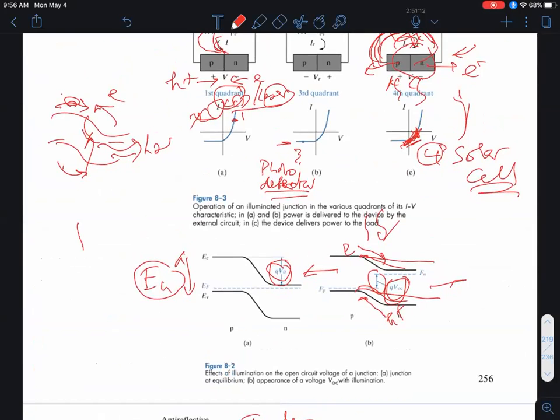So in a battery, the output voltage that you get out of it will depend on the electrode materials in the battery and the electrolyte that you have in the battery, okay? And interestingly enough, that output voltage does not change. The open circuit voltage does not change. Instead, what happens in a battery as you consume more and more of the material, suppose it's not a rechargeable battery, maybe it's just a regular alkaline battery, as you have more of this electrochemical reaction that goes on, this internal series resistance of the battery keeps increasing, okay? And that's what causes you to get rid of the battery, not because of VOC changing, but rather the internal series resistance keeps increasing, okay?